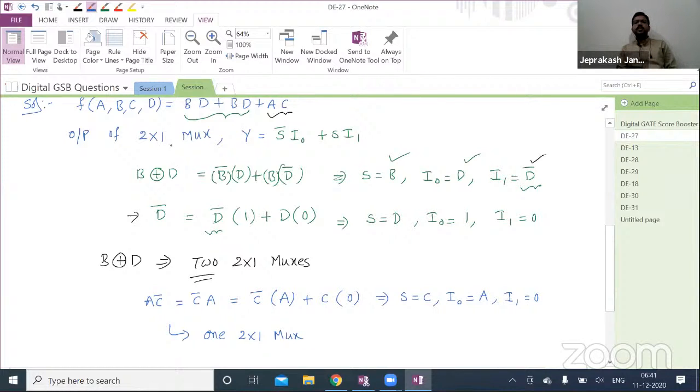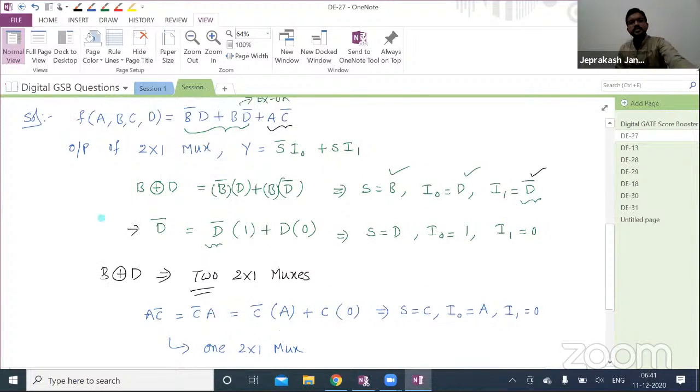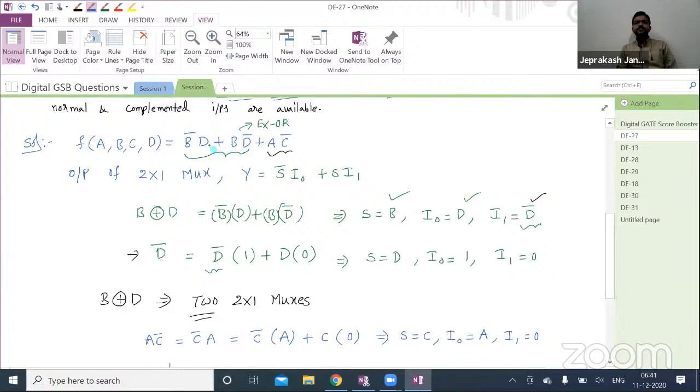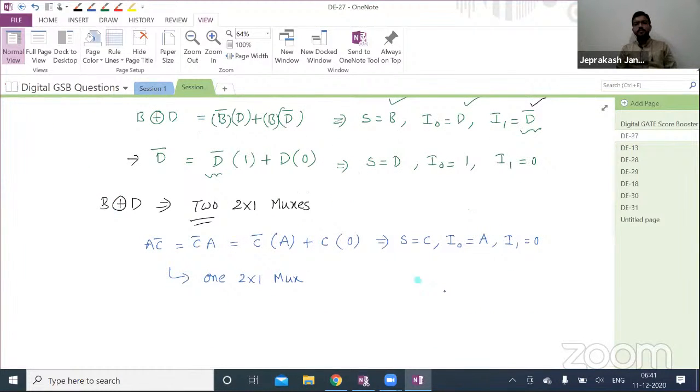Okay. So what we have done is, whatever the given expression is, we have made it into two parts. One part is the exclusive OR function, another is a logical AND, but with one variable in complement form, right? Now if you observe the overall function, just assume this entire combination is x1 and this particular term is x2. It is something like x1 plus x2, that means what? Logical OR. That means you have to implement the logical OR function, right? So just write the truth table regarding x1, x2, for the logical OR operation.